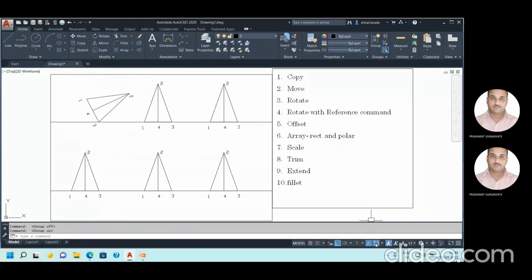Okay, let us see if it is off. Now it is off. Now if I go to the line command and I want to pick a point on the line, it is quite difficult to pick a point. You can see here, picking any point becomes quite difficult from this point of view. Okay, why? Because OSNAP is off. If the OSNAP is on, now you can see that you can easily snap to the corner points. Okay, so this is one of the commands that needs to be explained, for the exact connection of these points with the line.